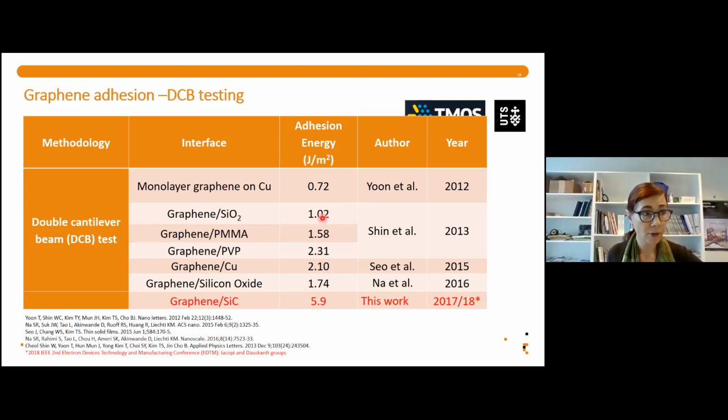And I know very well that because I worked for a while with materials that had that type of problem, which were porous dielectrics. And basically, in the end, for many reasons, and adhesion was one of those, we could not go for ultra-porous low-K dielectrics integrated into our common ICs just because of the adhesion problem.